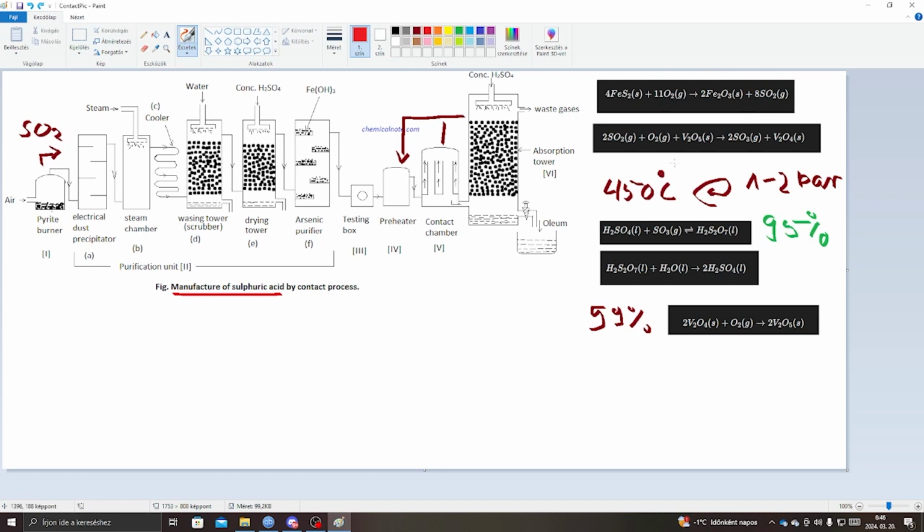They used to use platinum as a catalyst for the catalytic reaction, but platinum had some major issues, consisting of its price first of all, but also it works at higher temperatures, almost or even 2 times this temperature, so at like 800 to 900 degrees Celsius, and at elevated pressures. So the vanadium, because it is cheap, more efficient, and also easier to work with, is chosen and more desirable in this process.